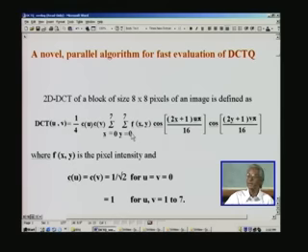It is actually that an average is a division by 64, whereas we deal with only 8 here. So it means 8 times the average information is contained in just one coefficient. In other words, if you take just the DC coefficient alone, code it and transmit it, and receive it at the other end and do the inverse operation, you will still recover the whole image. Only details may not be that easy to see, and you need much higher coefficients in order to create the detail, especially at the sides, be it vertical, horizontal or even diagonal, and so on.